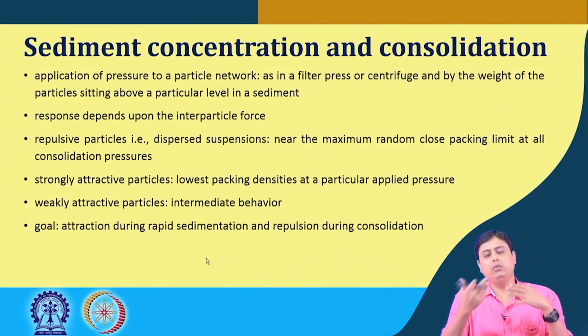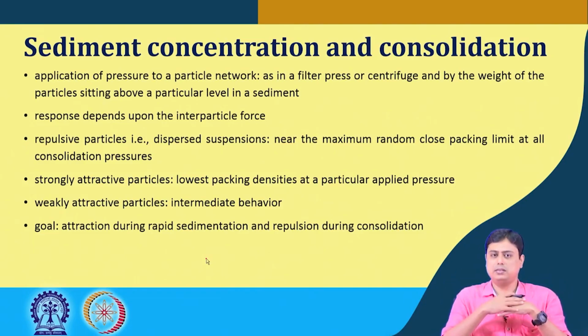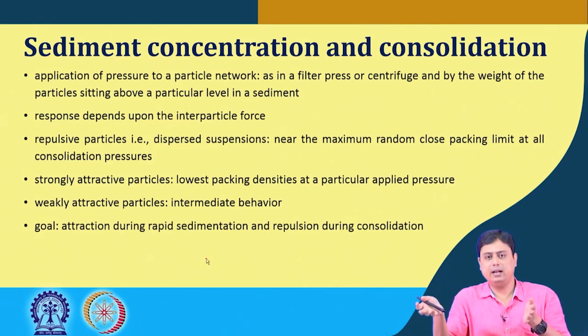So, this kind of tuning has to be done, and this is the current area of research, that we need a faster settling but with dense sedimentation. So, these are the impacts of the fundamentals of fine particles when we talk about solids handling.